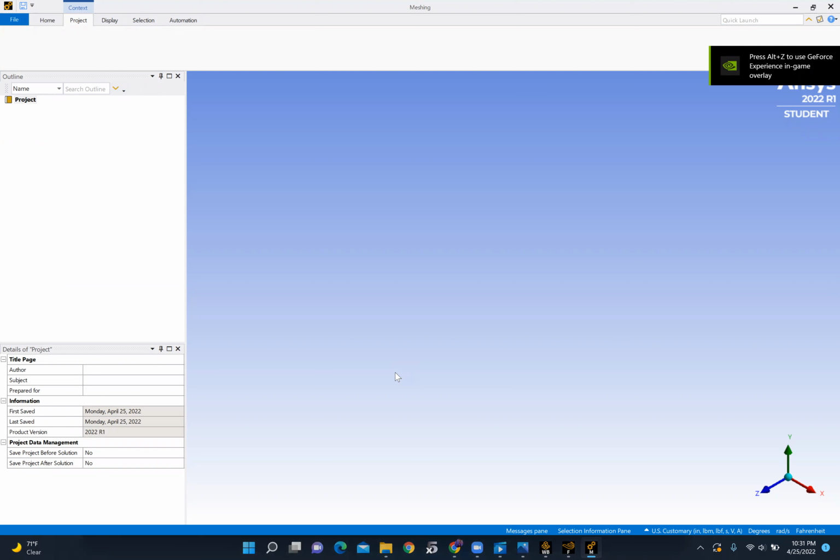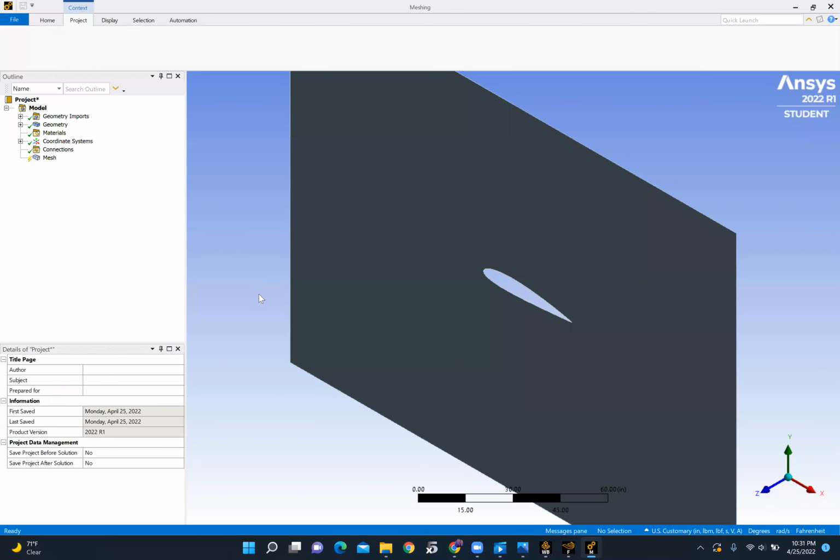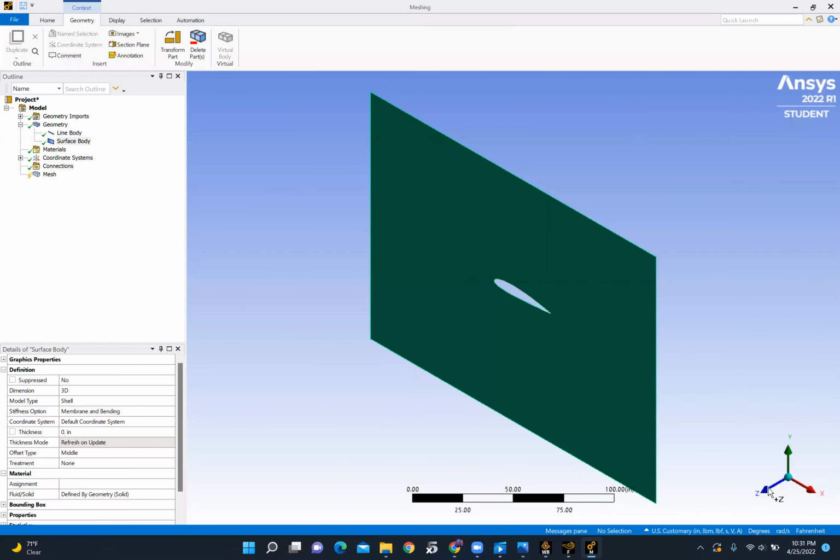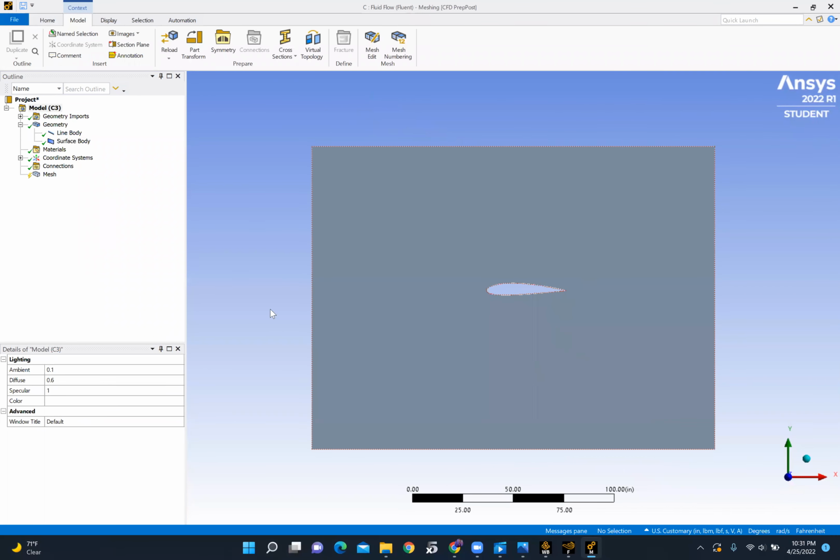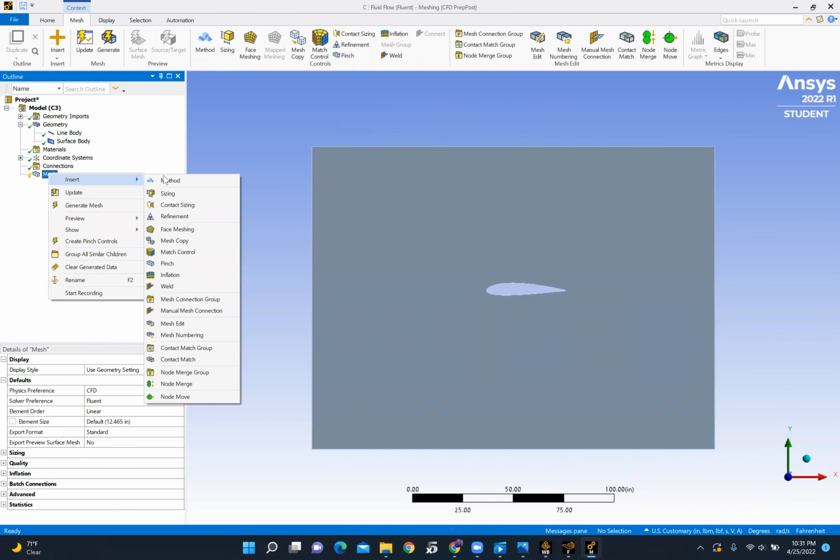So you'd want to rotate the airfoil before you make the rectangle around it. And that's how you're going to do the different rotations. It's a bit tedious because you are going to have to do it for every single angle of attack that you're looking for. So within here, it's pretty simple, straightforward the way you're going to do the mesh.